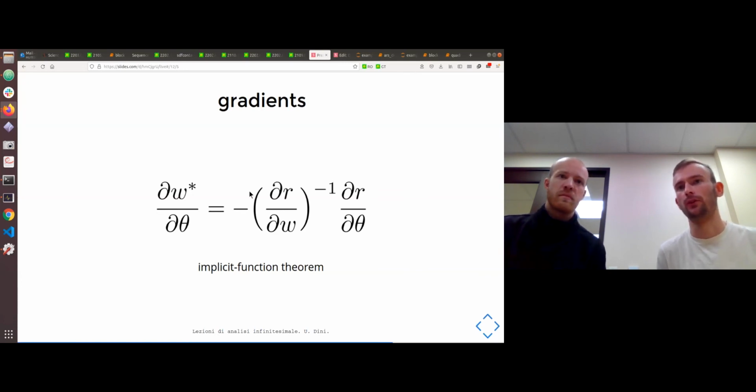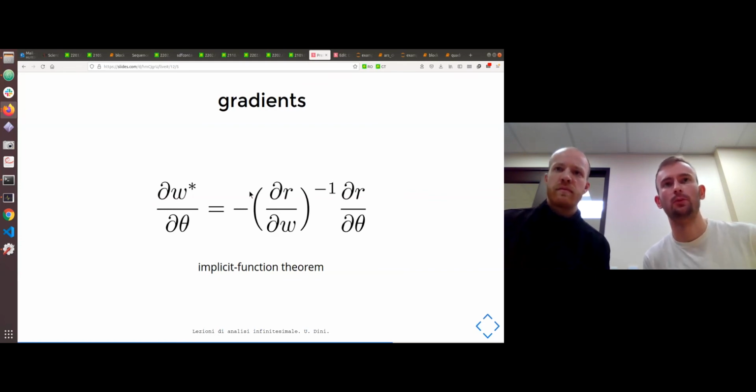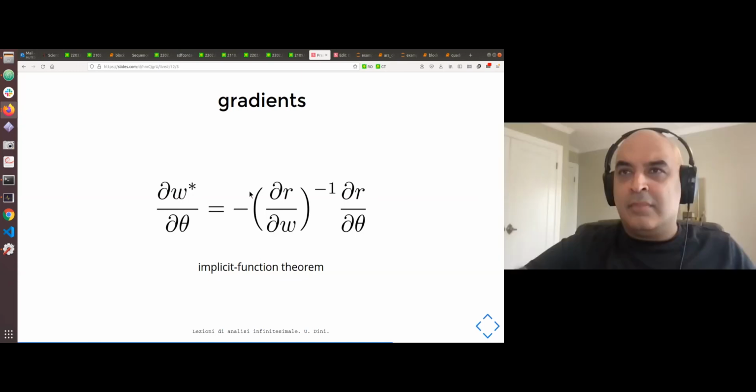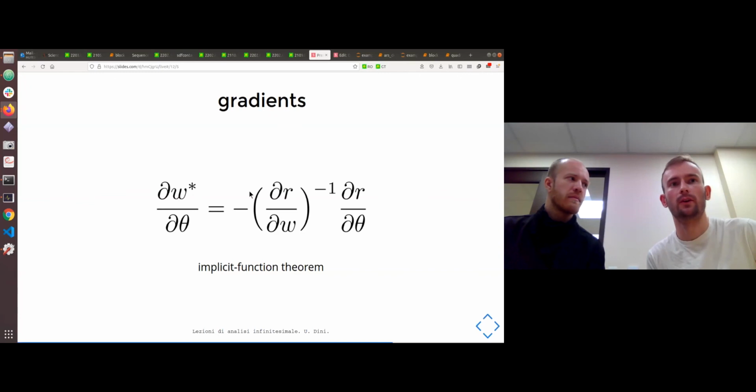But if you linearize all of those quantities, the contact and the friction, the signed distance function, the dynamics, I guess this should be feasible, and this is what we are doing with a previous work that we've done together with Taylor. This is the CI-MPC work, so contact implicit MPC, where we have a reference trajectory that we want to track. To track this reference trajectory, we are linearizing the free-floating dynamics of the robot. We are linearizing the signed distance function, all the contacts. And then with those simplifications, we are able to run an MPC loop at real-time rates, but I think we are not ready yet to do the full nonlinear thing, especially in real time.